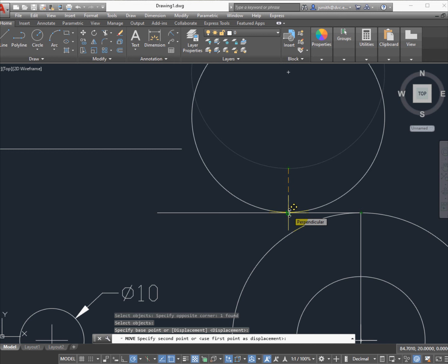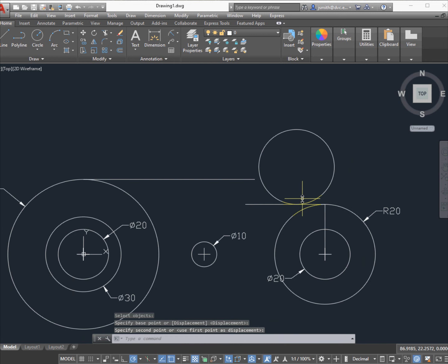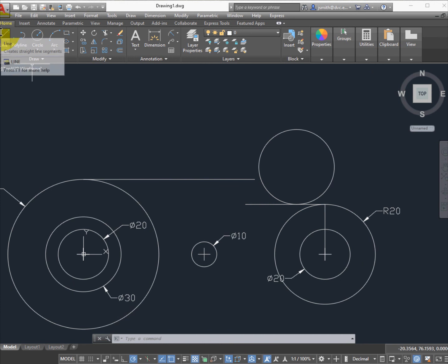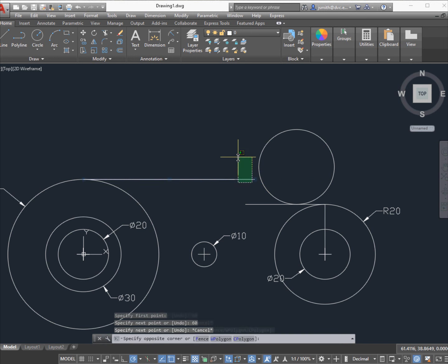And this is tangent, right? So this is at the bottom of the circle. And now all I need to do is type and move. You might want to play around with this a little bit, but you'll notice here. So I'm going to go ahead and just make sure I have this done here. I'm going to make this line 60 millimeters. So type in 60, push enter, and I'll delete that first line that I made. We don't need that. So the larger line is gone.